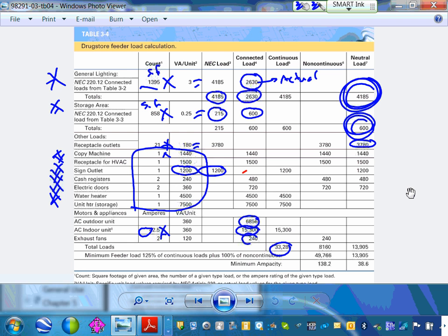Look what they do. If they're continuous load, guys, they put them on their continuous and they multiply them by 1.25 at the end. And finally, my friend, they add the neutral too. Can you see that they're adding them on the neutral and putting it with their continuous load here, like we did, continuous load or non-continuous load? Because what's the difference? The continuous you multiply at the end by what? 1.25. All the way to the end, gentlemen. And they came up with this number for the phase, this number for the neutral.